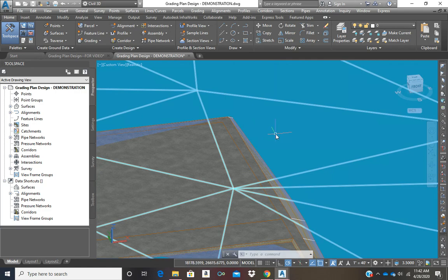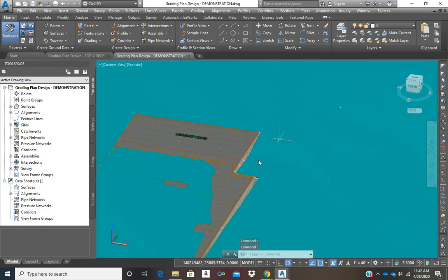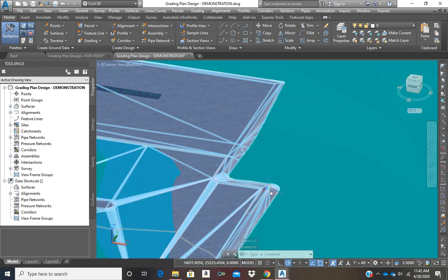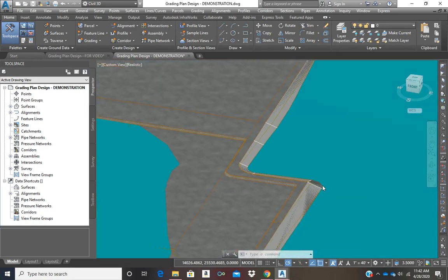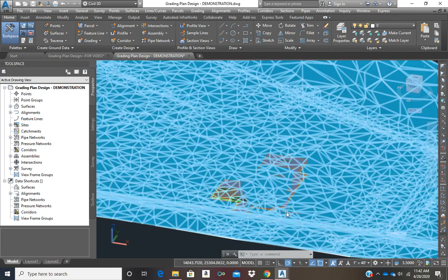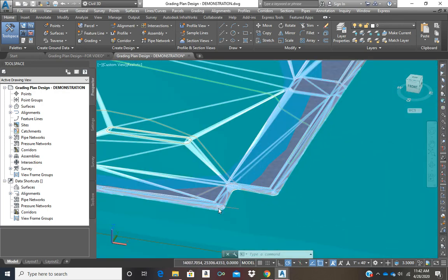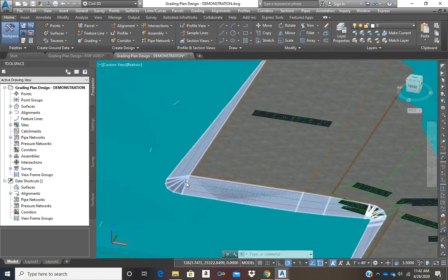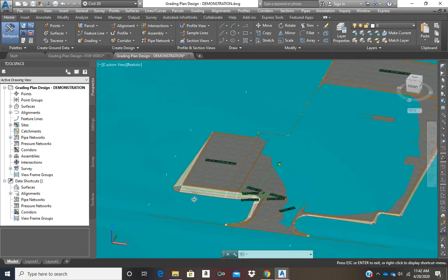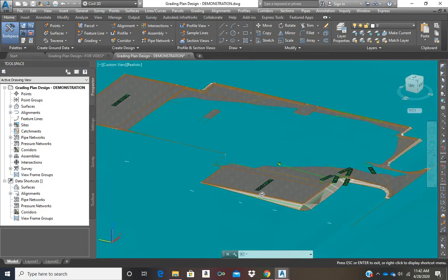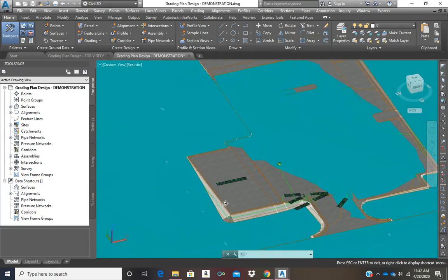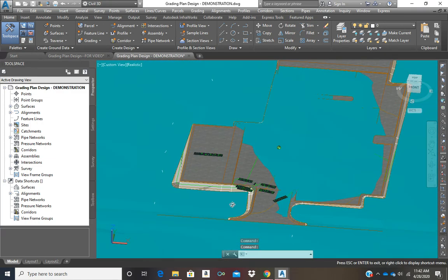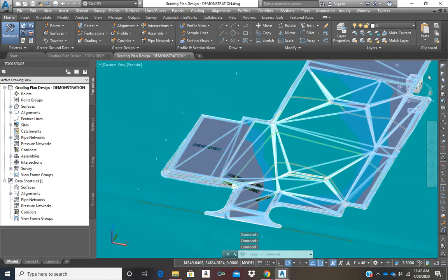So we'll put in that 2-foot bench also with a stepped offset. And then after we finish that edge of the bench, we will then daylight that one using a create grading command in Civil 3D to then daylight the edge of the finished ground surface down to existing ground and finalize our design. At that point, we will be done with the design, and then we can start putting in our spot elevations to indicate our final design grades of our site.